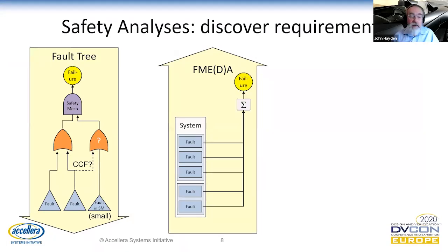And then I figure out how they're all going to combine to contribute to top-level faults or violation of a safety goal. Now, in safety, what you're going to do is line up safety mechanisms for the most significant of these failure modes and evaluate their failure rates and diagnostic percent coverages, how effective they are at controlling these faults, and then evaluate your overall metrics.